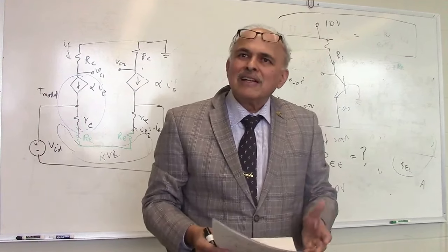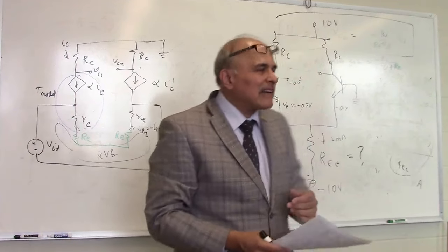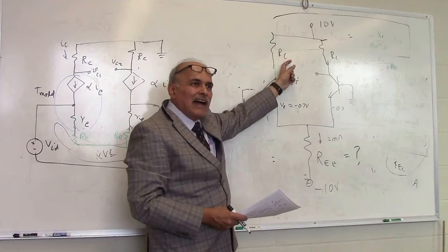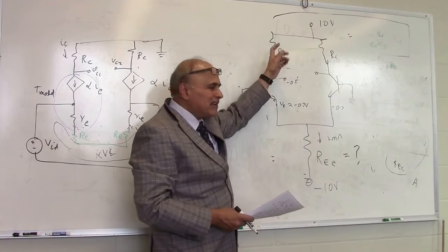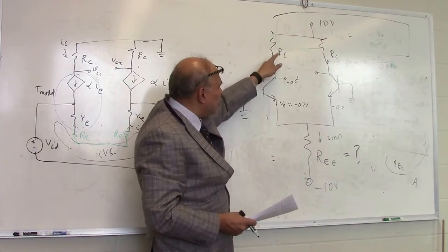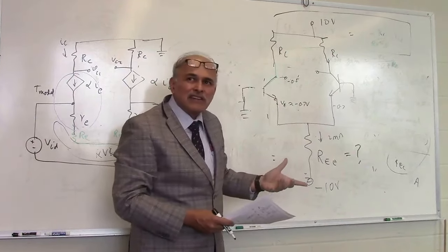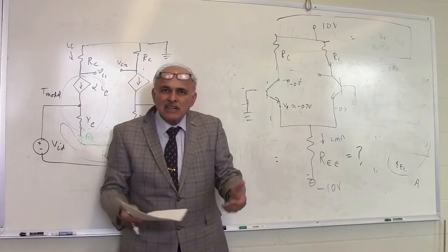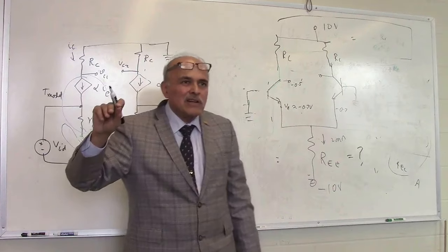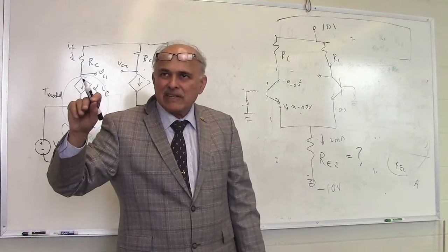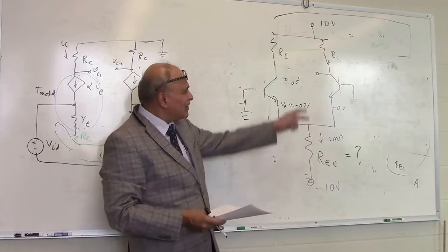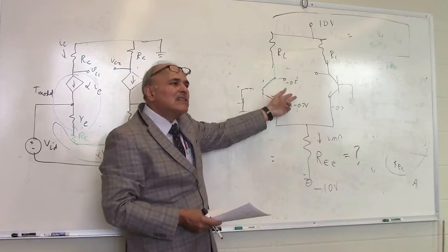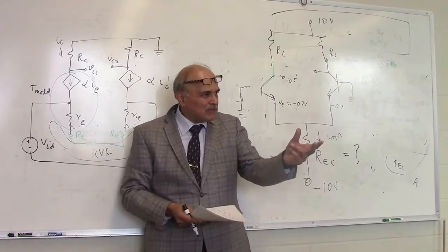All right. But you have some practical limitations. You can't really choose RC as anything. If this is 1 milliamp, I have to choose realistic resistors. So if I want it to be exactly 5 and this is 1 milliamp, then RC should have been 5K. Can you get a 5K resistance? You can make one, but it's difficult. What is the closest out of the box value for a resistance? 4.7K, plus minus 5%. So if you put 4.7K, you get 5.3 here. That is 10 minus 4.7 volts. Good enough because you're only required to do plus minus 7.